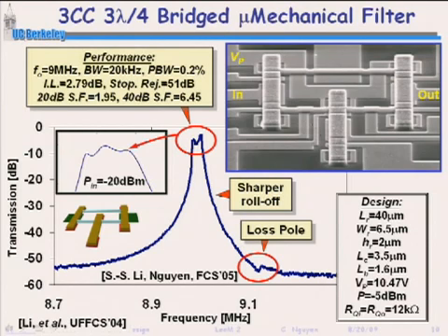on this at lower powers, looks like a filter transfer function. This was attempting to be a Chebyshev type filter. It even has sort of a loss pole here, which was also attempted on this. But in the end, it's the lateral dimensions of all of these things that specified an equivalent circuit that gives you a filter. And in fact, you can really call this an electronic circuit by just equating all of these things. So if I look at this thing, I can make some equations.